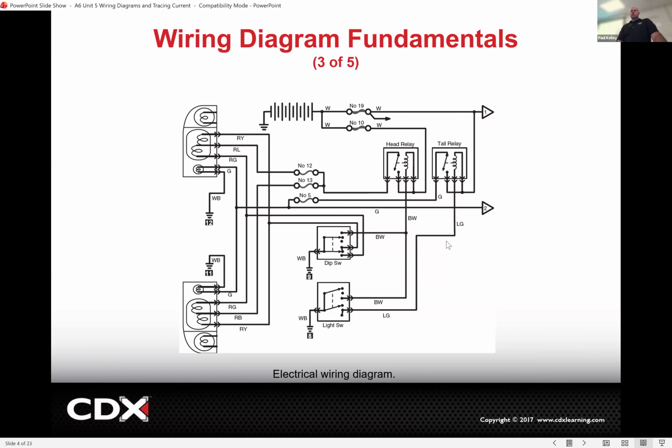Now, what this doesn't do is tell you where anything is. So if you're looking for this fuse, it doesn't necessarily mean it's 1 inch from the battery. It just means electrically that's how it's laid out. So if you want to look physically for that fuse, well, that's a different thing. That's not really tracing wire diagrams. And I actually pulled it up on another screen so I could show you, like, there is a way. That's component view. That's component location. So if you want to do component location, that's not a wiring diagram. The wiring diagram just shows you electrically how it's laid out, not physically.